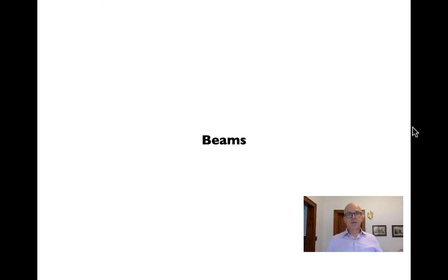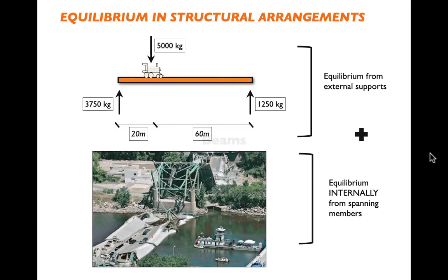We then come to beams, what slabs frame into, and here we have a slightly longer process to go through because we have to figure out the loading on the beam. We then have to go through and figure out, based on the section modulus, whether we've got sizes that can carry not only the load that we're putting on them, but also their own dead weight.